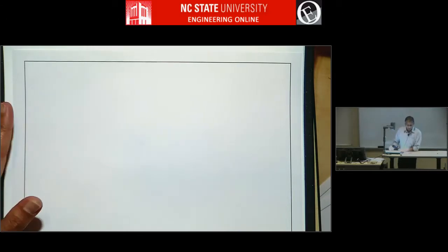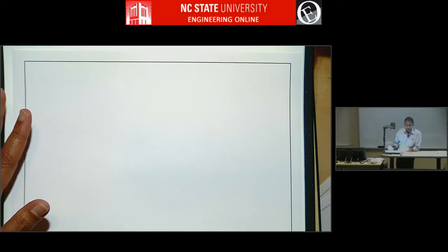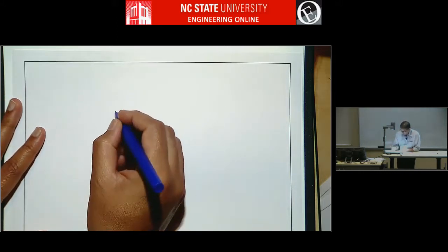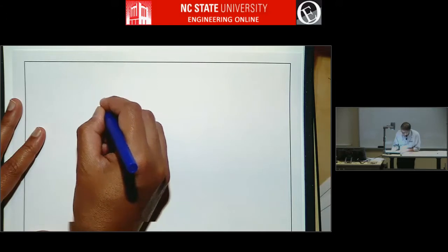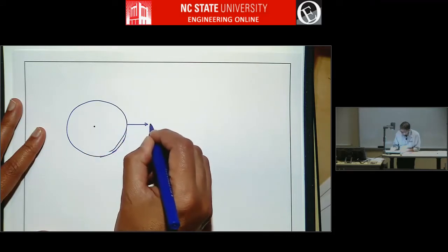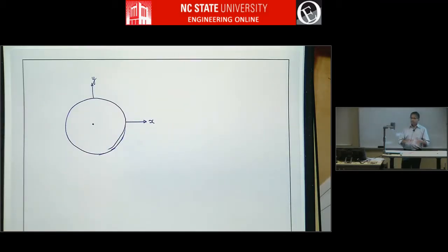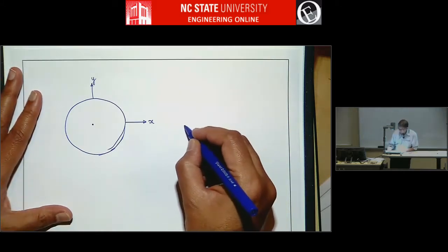So let's use a sketch and talk about how these segments look. You kind of have to think about the circle geometry to some extent and the airfoil geometry together. So let's talk about a circle here. This is a circle that's used in conformal mapping, and although you won't be actually fiddling around with any conformal mapping, the inputs you give will determine the transformation function that takes the flow around the circle and maps it to flow around the airfoil. And then here's the airfoil.